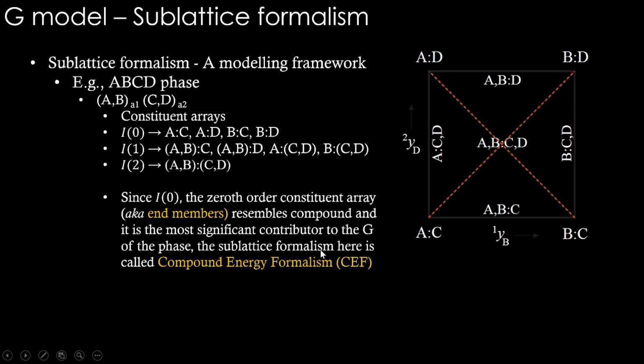The sublattice formalism here is called the compound energy formalism, CEF. So instead of saying sublattices, people use the term CEF, compound energy formalism. So don't be confused, it is essentially sublattice formalism. Because of this reason, it is called compound energy formalism. So these are the different terms that we wanted to understand about sublattice formalism: constituent array, end members, compound energy formalism, site fractions. So all these things we have covered now.